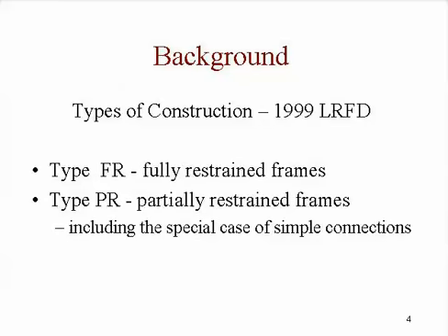Now, when we got to the 1986 LRFD specification, and then right up through the 1999 LRFD specification, the Specification Committee chose to redefine the types of construction. And so they defined Type FR, which was fully restrained, right, rigid connections, and Type PR, which was everything else.